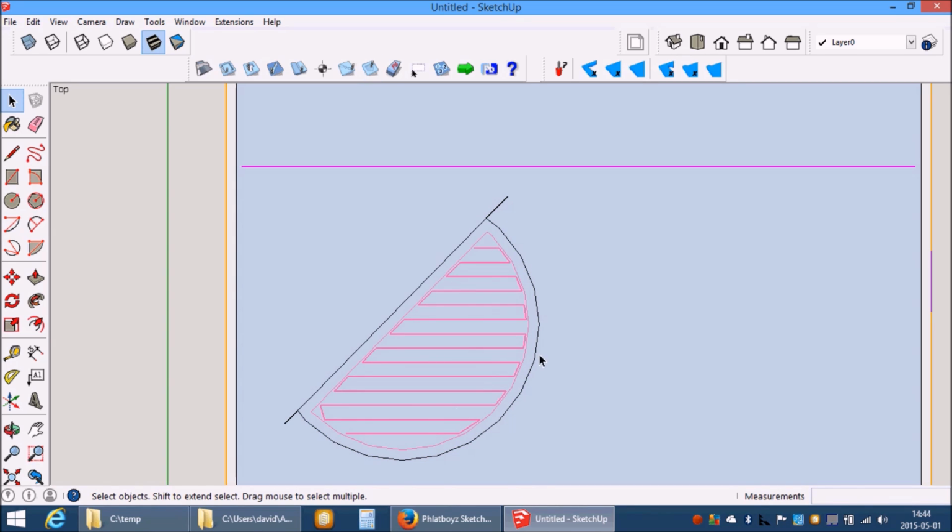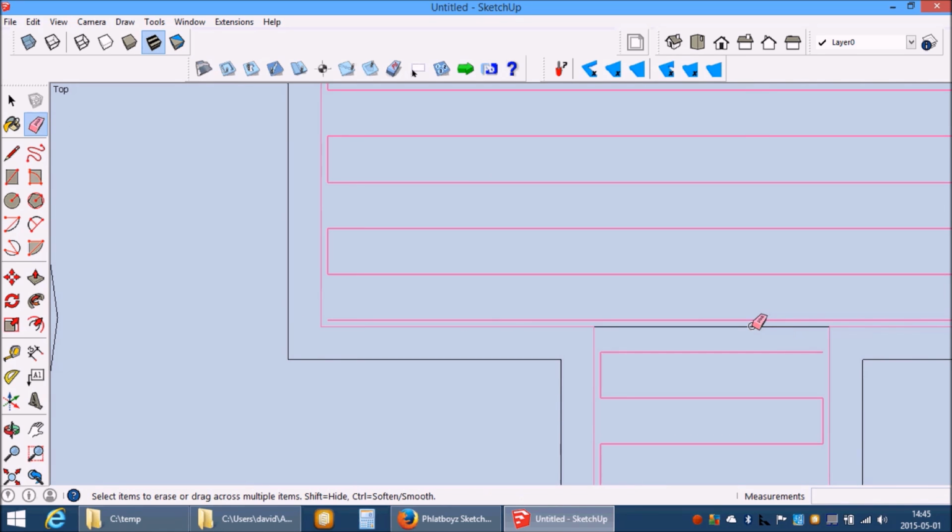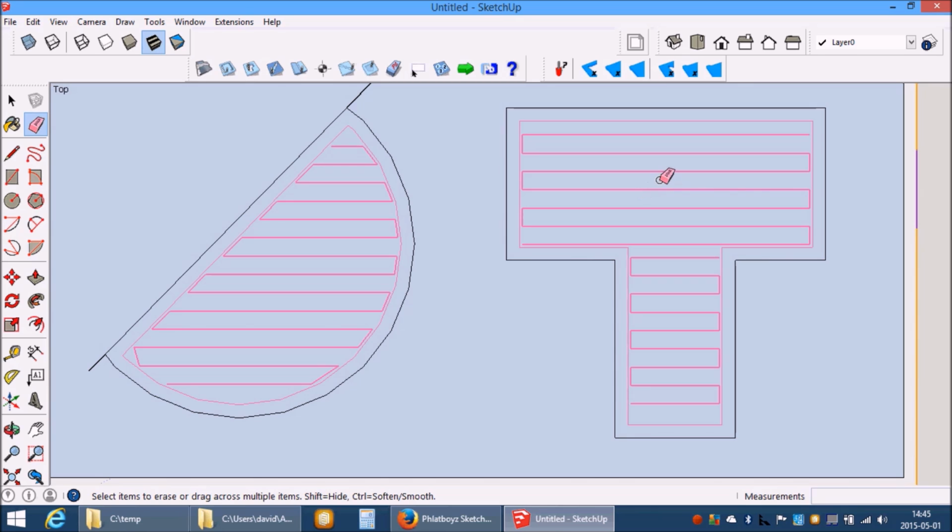The reason for being able to separate the outline from the inside is for complex objects like this. As you can see, there's little blobs in the way it generates the zigzag, and so if you hold down shift, you get only the zigzag. It looks worse. If you hold down control, you get only the outline. Click. I can now draw a line from there to there. Reselect the pocket tool, hold down shift, zigzag that bit, zigzag that bit, and I can erase that extra line, and that pocket will now cut perfectly. The outline being one continuous tool motion and the two zigzags cutting before that normally.